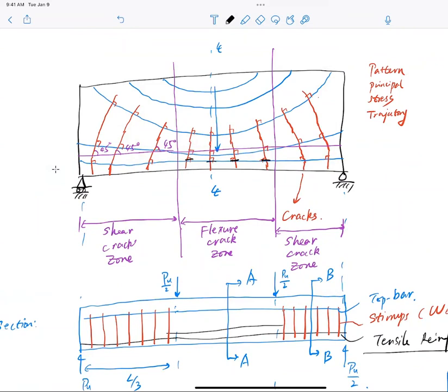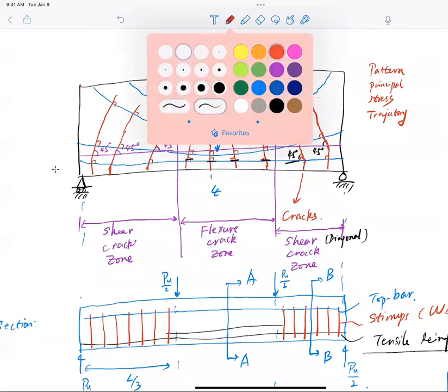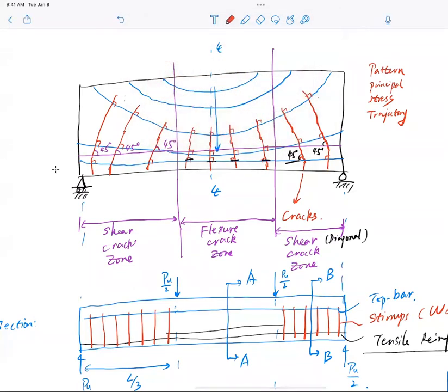But in the diagonal or shear crack, or we also call it diagonal crack zone, okay? This is 45-degree diagonal direction, okay? Keep this number in your head, 45-degree, because I may ask you a question in exam number 2, okay? And this is called diagonal crack zone, right? It's very hard to just use horizontal reinforcement to stitch it over, isn't it? So now to stitch a 45-degree angle, we normally just do a straight line.